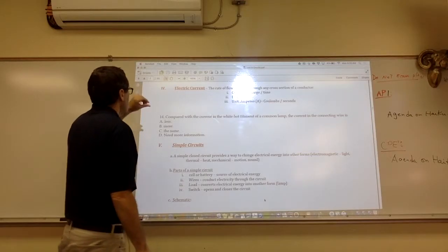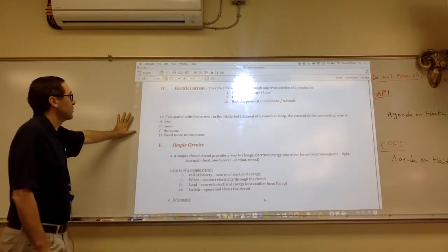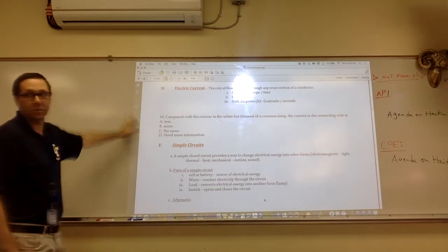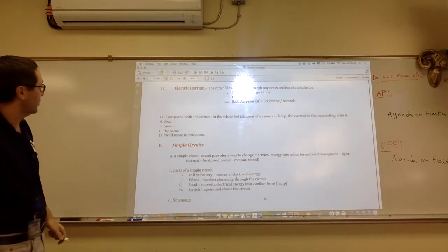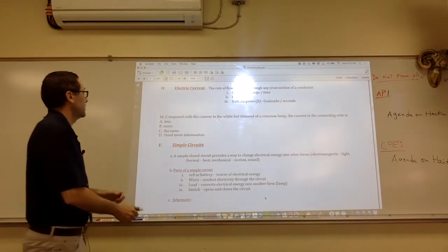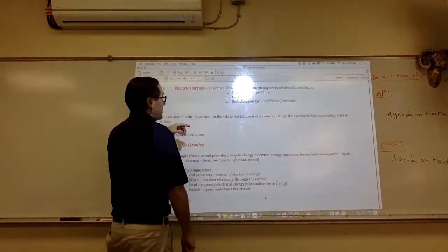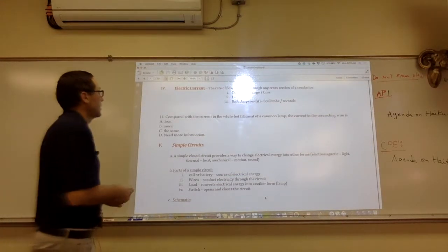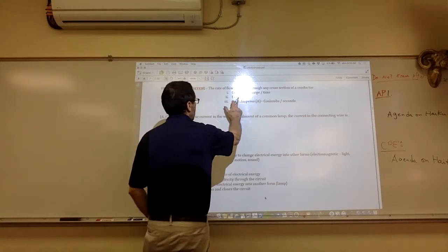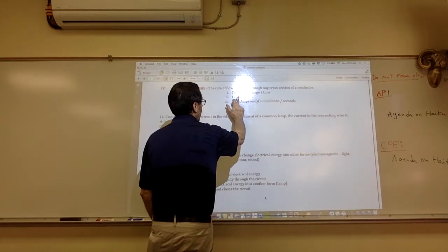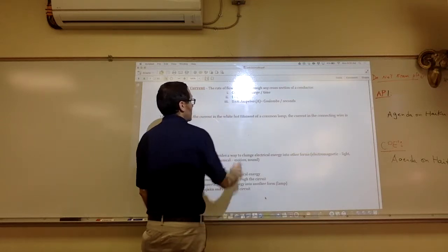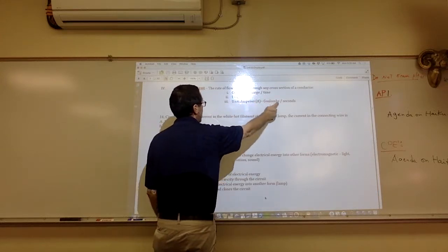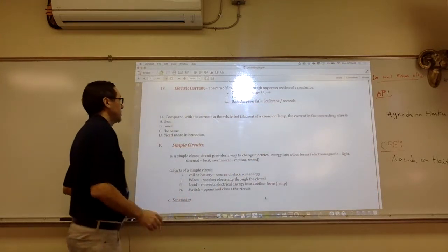This video is going to talk about electric current and how to make a simple circuit. So we're going to start with the foundation to DC electricity. DC stands for direct current, so we don't do any AC current here. Now the definition of current is how much charge flows through a wire per second, per unit time. So the unit for it is amperes, which is basically coulombs per second.